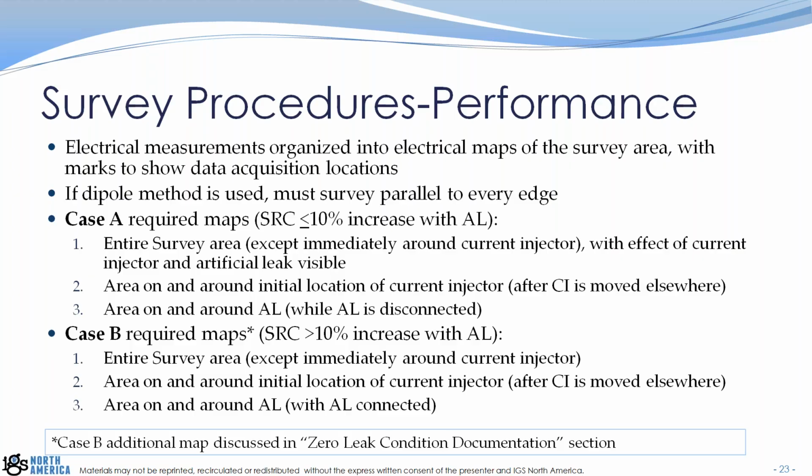And when you survey an area, you're always going in one direction back and forth. So you have to make at least 2 more passes perpendicular to the direction of the survey on the edges that you were always approaching and traveling away from.